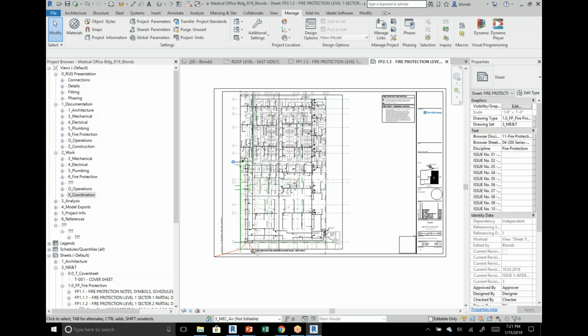So a recent healthcare project we were working on, where every single trade is going to be involved, I actually split the model into 3. I've got an electrical, fire alarm, and nurse call file. I've got one for plumbing and fire protection and med gas, and then I've got one more for mechanical ductwork and piping. That's just to help keep some separation, and then all of those will load in the other files to it. So I've seen, from the small standpoint, a single architectural and structural file loaded into all of MEP.